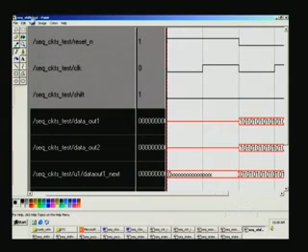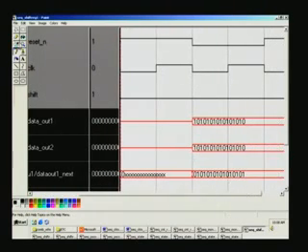So what is happening here: whenever there's a reset that's active and the clock is free running, it can start any time or after the reset, and it doesn't really matter because reset is asynchronous active low. Asynchronous means whenever that happens, immediately it will take effect, whereas in synchronous, it will take effect only when the clock arrives. So this is asynchronous for the reasons we have already covered earlier. And we see that this data out is preset by this value whenever reset is encountered. That's why you have the same 1010 appearing here.